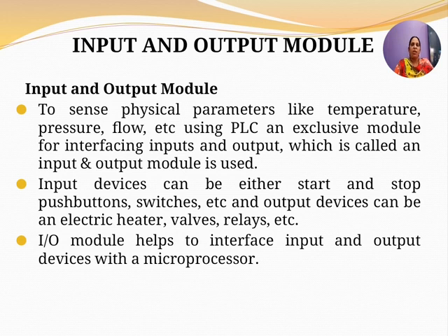The input-output module senses the various physical parameters. An exclusive module is used for interfacing the input and the output, and that module is called the input-output module. The input devices can be used to start or stop a process using push buttons or switches, etc. The output devices can be an electric heater or a valve or a relay, etc. So the input-output module helps to interface input and output devices with your microprocessor.